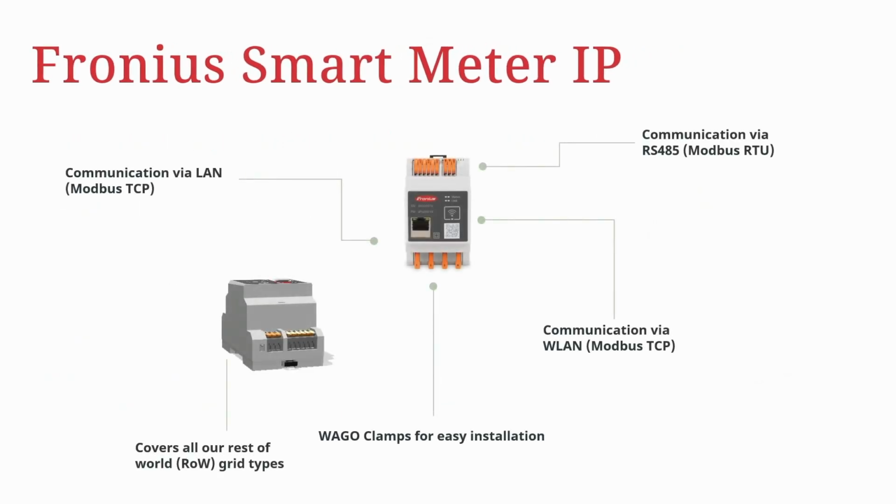On this slide, we have an overview of all the communication options that the Smart Meter IP brings with it. First of all, we have communication via Modbus RTU, so via RS485. This is the common connection that we already had on our previous smart meters. On the other side, we added some new features on this smart meter.